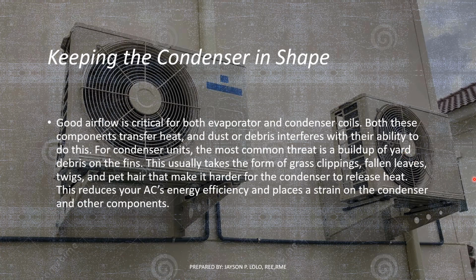Ice on the condenser can also be caused by low refrigerant, which requires a call to a technician. When the cooling season ends, protect the outdoor condenser from the elements by covering the top with a piece of wood held down at all four corners by bricks. This keeps snow or any materials from piling up inside. So I think we are done with the evaporator and condenser.